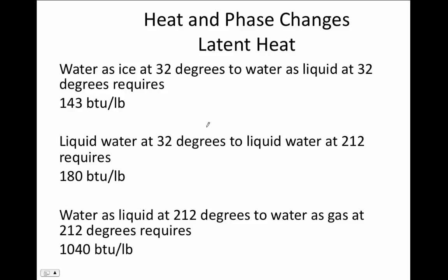So the wax was solid, it melts, it turns into a liquid, and then at night when the building starts to cool off, say it becomes 70 degrees and the barrel's at 80, the molten wax at 80, it'll solidify back into solid wax, and it'll give back large quantities of heat. So this phase change is sometimes used for heat storage systems in buildings.